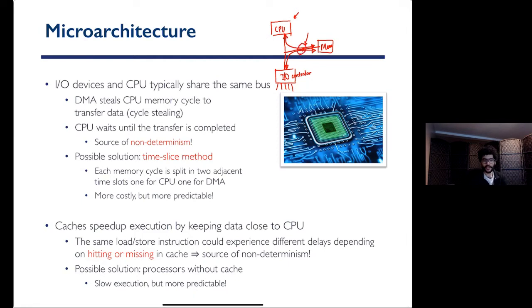the DMA engine requests and the task that is running on the CPU, both of them are competing for the bandwidth of this memory bus. And this could slow down the real-time task that you're running, or could add some uncertainty or some randomness to the performance of the application.